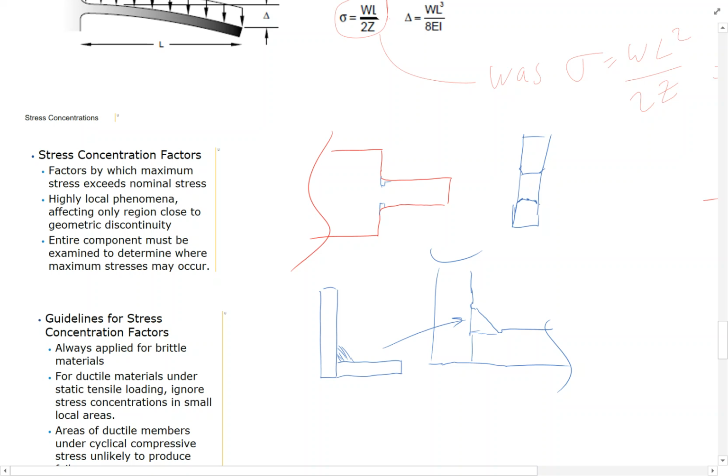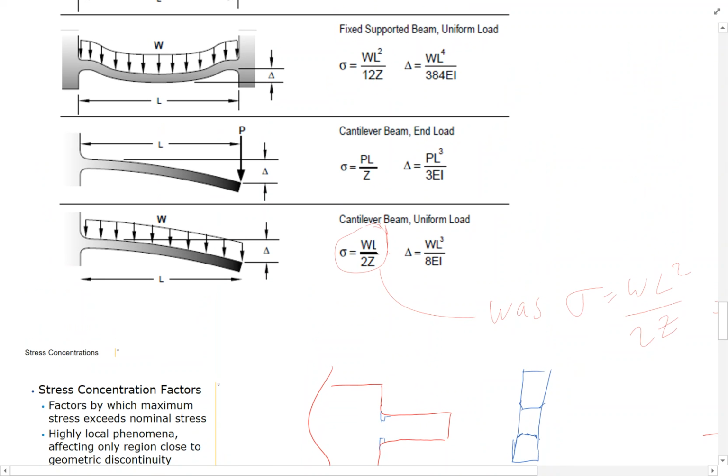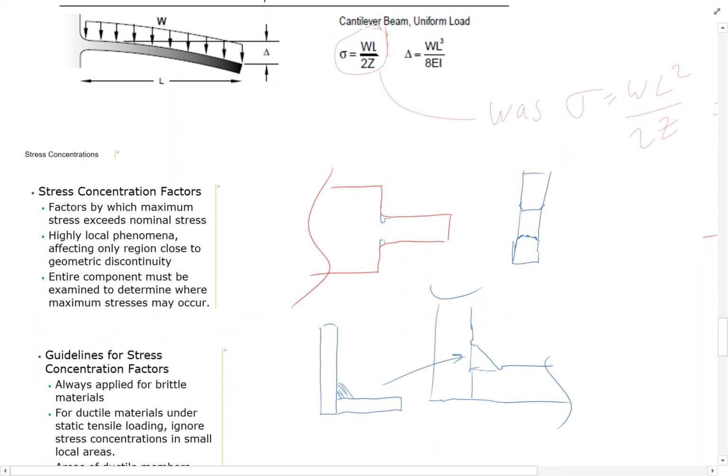Well, because it's really pretty easy to do this kind of stuff, right? Pretty straightforward. Real easy now with FEA, assuming you apply it right, you've got your loading conditions correct, and you did a good model. Very easy to calculate loads, just looking at stress, right? I can easily calculate what the stress is in my structure. I can easily calculate what my safety factor is going to be because I know what my yield strength is. Well defined, well understood. Fatigue comes into play because it's a cyclical process, and we will do some analysis of that too using FEA, and that's helped things a little bit. But it's much harder to understand.